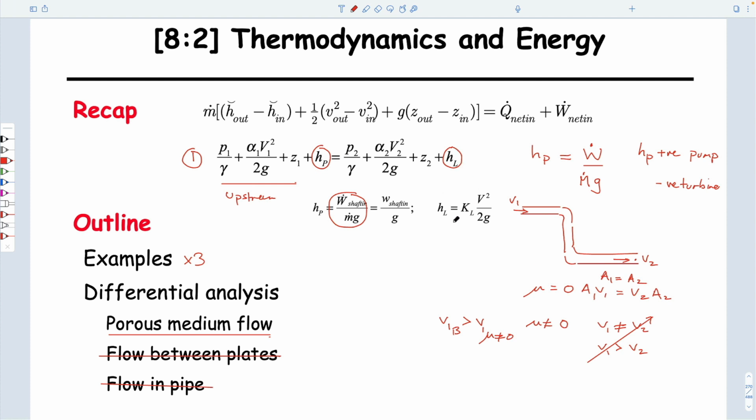And the point I was going to make is that these losses are due to what are called minor losses, which are given by an equation like this, which we'll talk about in pipe flows, which is a loss coefficient, which is some number KL, which is typically less than 1 and greater than 0, which operates on the velocity. And it just accounts for the fact that the water's happily going in the x direction, then all suddenly, rudely, it has to go in the minus z direction.